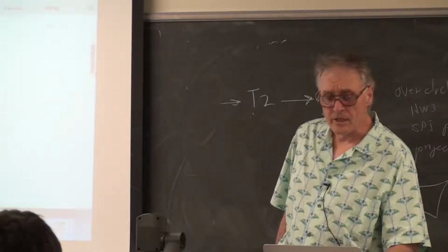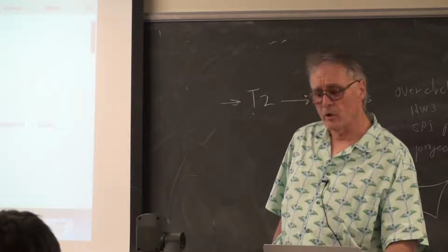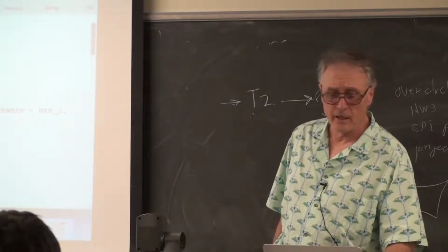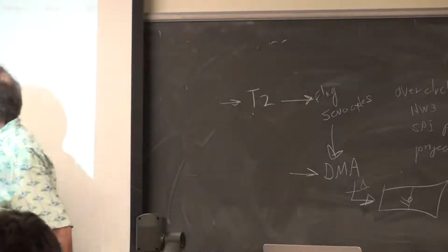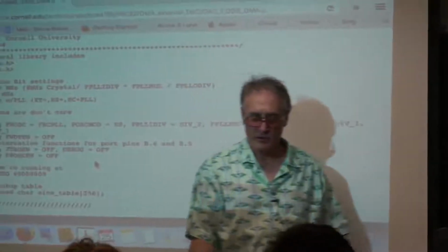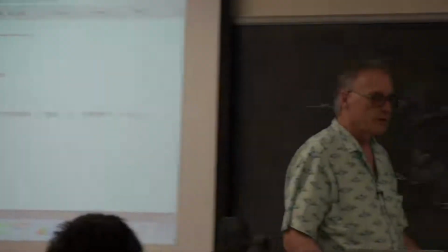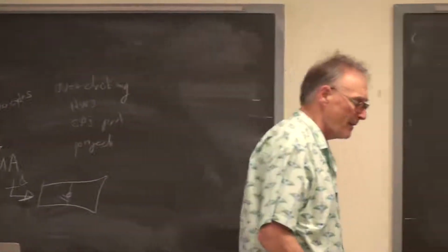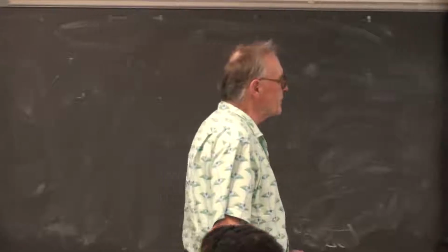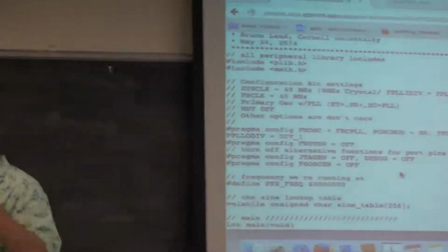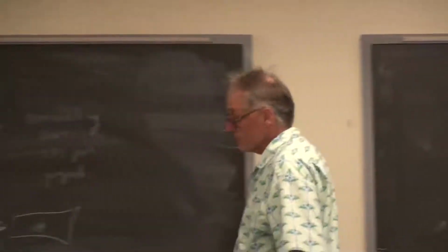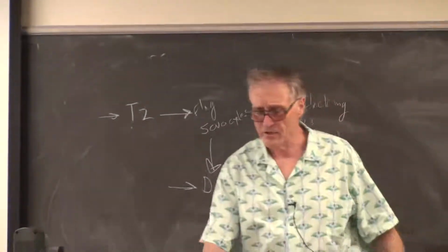And because I wrote this fairly early on when I was writing code, I put all this setup stuff in main. Don't do that. You're using config.h to set all of the config parameters for the CPU. You don't put any of this stuff in main. In fact, you put as little code in main as you can, put everything else in a thread.